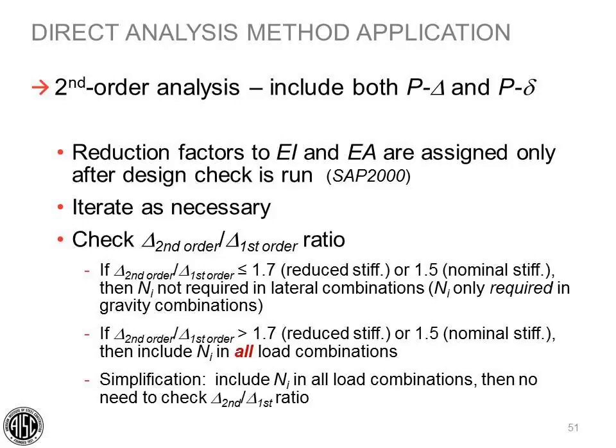I think there's a couple different methods. One is to just manually apply all those loads. Another is to find out what your typical ratio would be and then adjust your load factors on those other lateral load combinations to factor them up accordingly. So those are two different methods, but the notional load should be included.